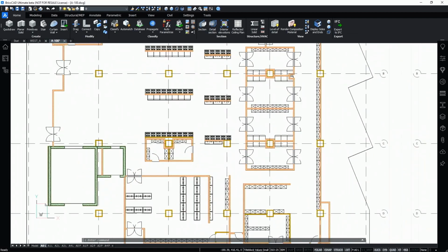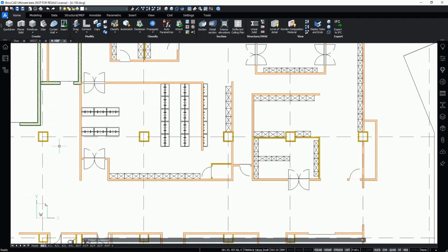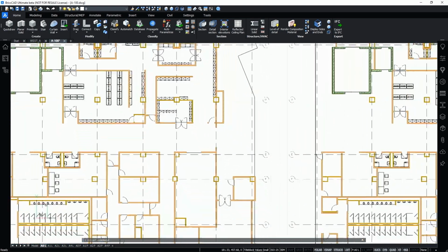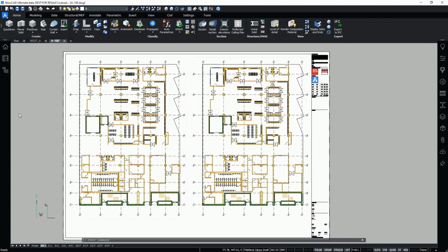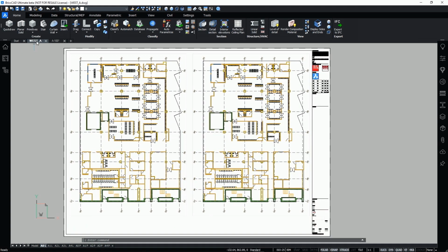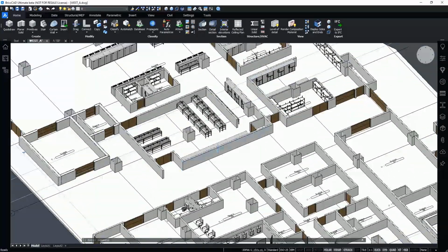Thank you. In this demo, we start from a sheet with two viewports of the same section result. The end goal is to create two types of customized plans, namely a life and fire safety plan and a space area plan. And we will do that using the drawing customizations as explained by Jürgen. Drawing customizations are closely linked to properties in the BIM, so we first go to the 3D model view.